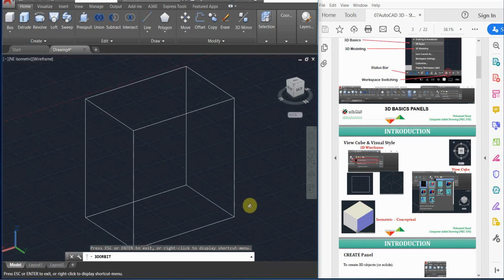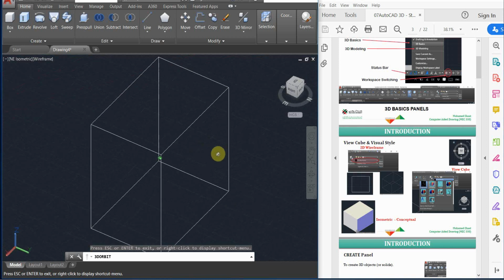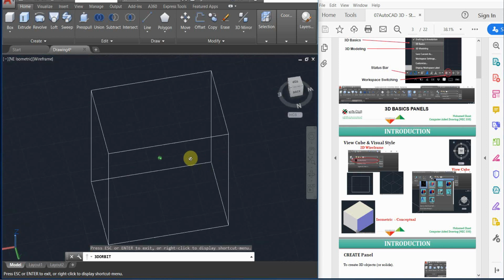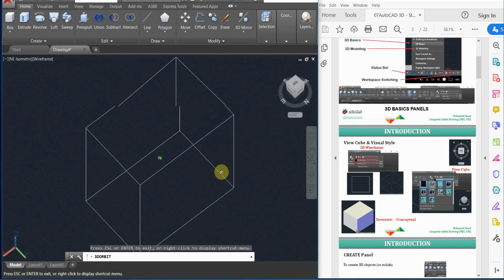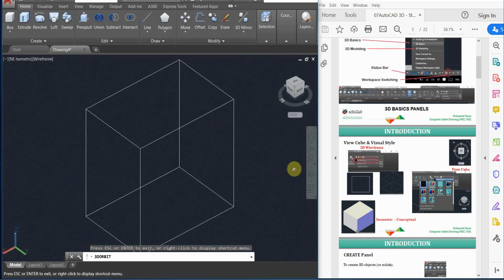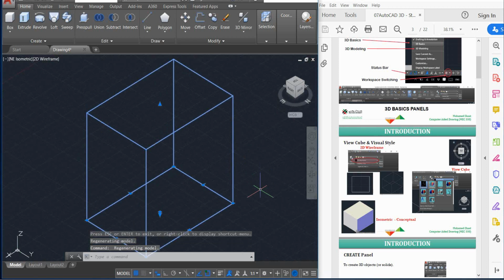And there is an option, by the way, in AutoCAD that we can record this movement. Just observe this view box. As we give rotation, we can keep recording this kind of motion of the object. So we're going to end up with an animated movie of this 3D solid if we are interested in fancy representations of these 3D solids. Make sense? So these are different ways we can change the orientation and change the view, how we look at this 3D solid.